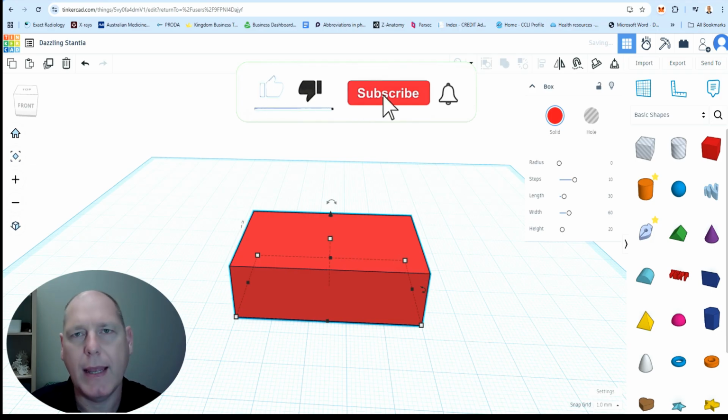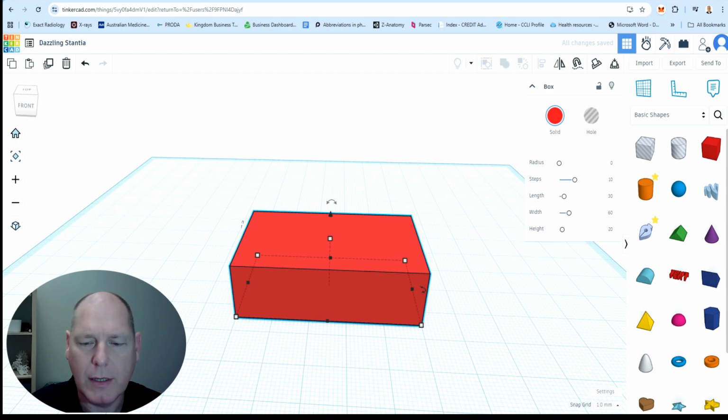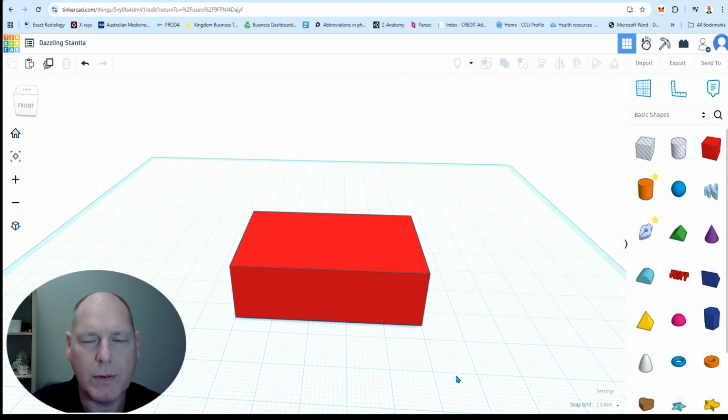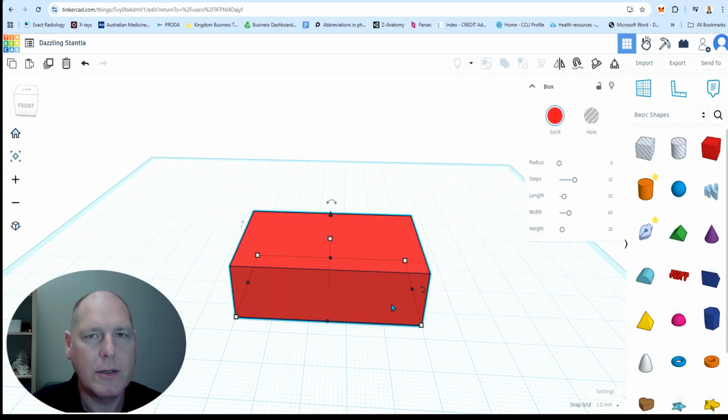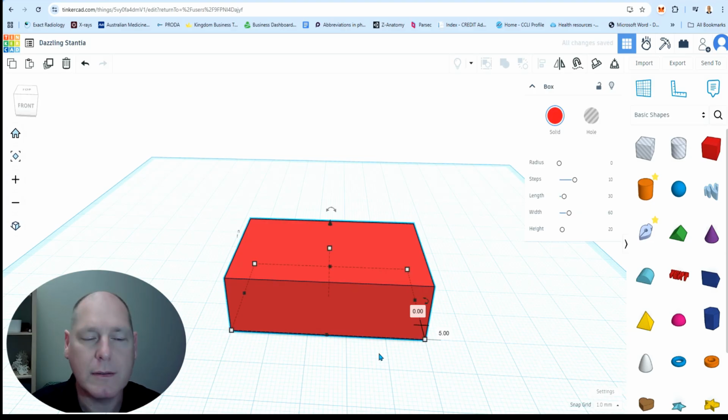These are very handy when you do designing and you want to nudge it just a millimeter, or you can even set your snap to grid down all the way to 0.01 millimeter. You want to nudge it just that little bit to make sure that you don't overshoot it, because when you use the mouse, it's very easy to overshoot or undershoot like that. So that's the usefulness of using arrows instead of the mouse.